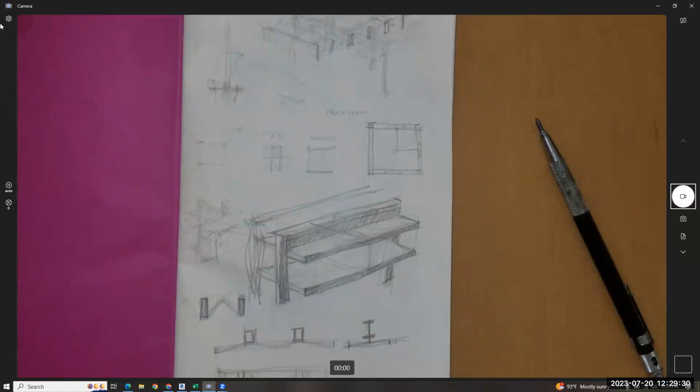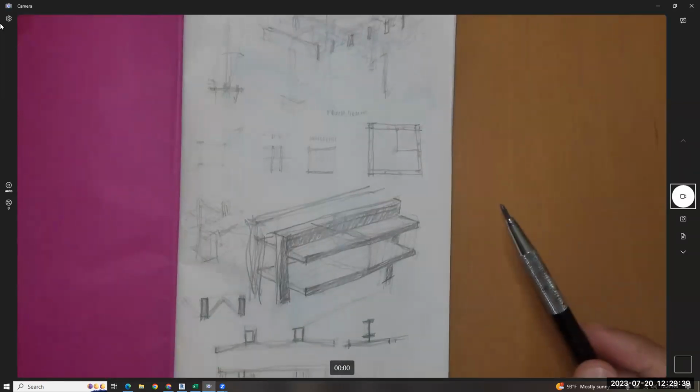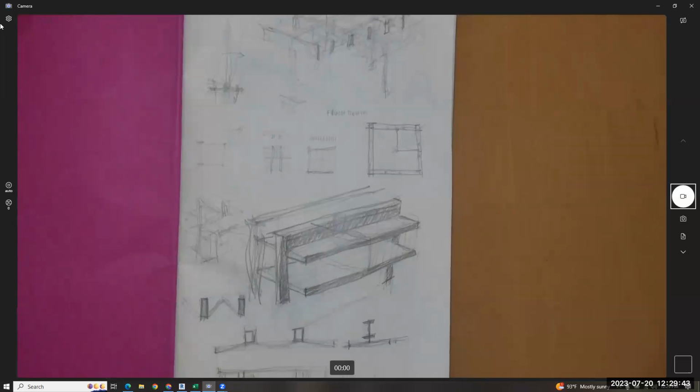Are there walls in either of the X and Y? Are there walls in X or Y? No, there's no walls in X or Y. So it's automatically not shear walls in X and Y because there's no walls. Okay. Is there X bracing or knee bracing in X and Y? No. So it has to be a moment frame, which is that they are. They're giant concrete moment frames.